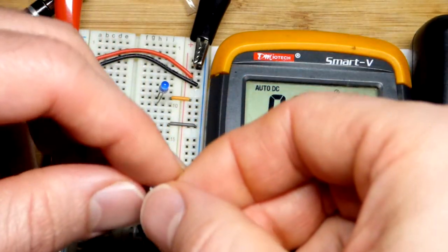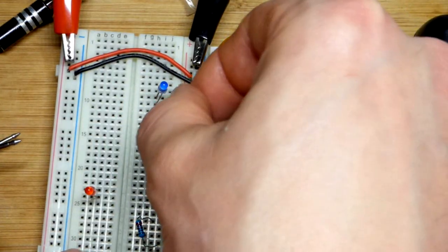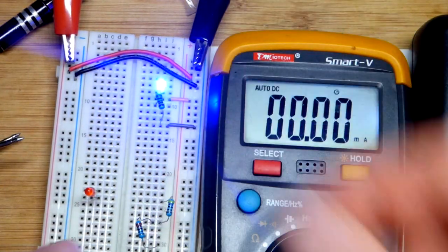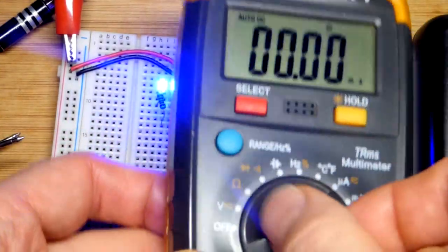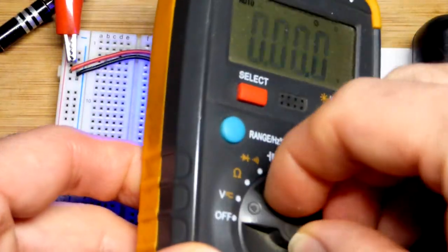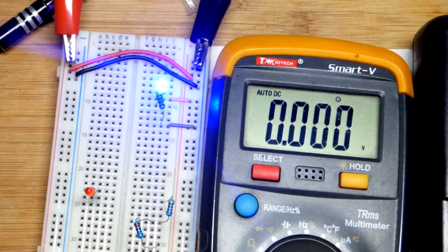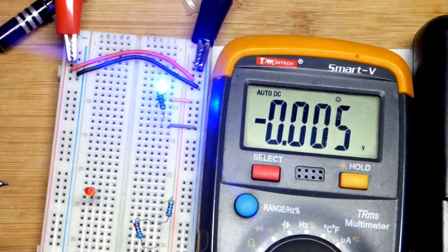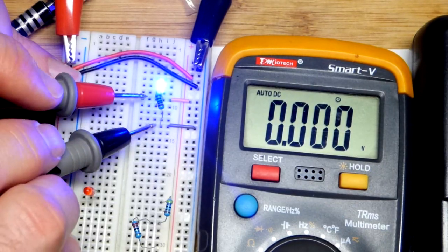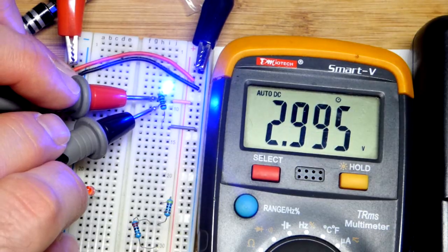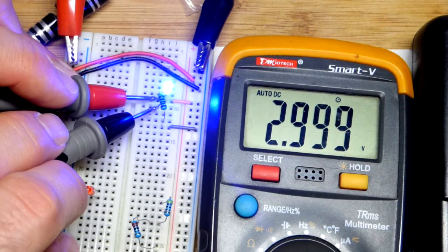So as you get higher voltage, the voltage drop of the blue LED compared to the red LED is not going to make as big of a difference, because you got more voltage to work with. Now, I definitely don't want to measure current by accident. I'm not going to even accidentally do that. And I got the power supply limited to 20 milliamps of current, so we're not going to damage the meter. But that's something you never want to do. Accidentally put too much current through a meter.